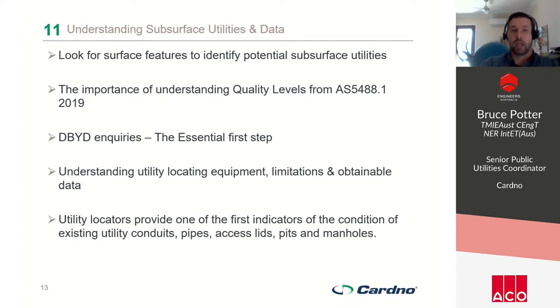The other thing to note for most engineering professionals is to understand the utility locating equipment that is available, and to understand the limitations and what you can actually get out of that data. That is very handy when you're looking through information provided by a surveying company or a locating company, and you're trying to understand what information you have. And then probably the last and most important thing is utility locators. They are one of the first to give us an indication that there is something wrong with an existing asset, being a conduit, a pipe, the access lid, the pits, or the manholes.